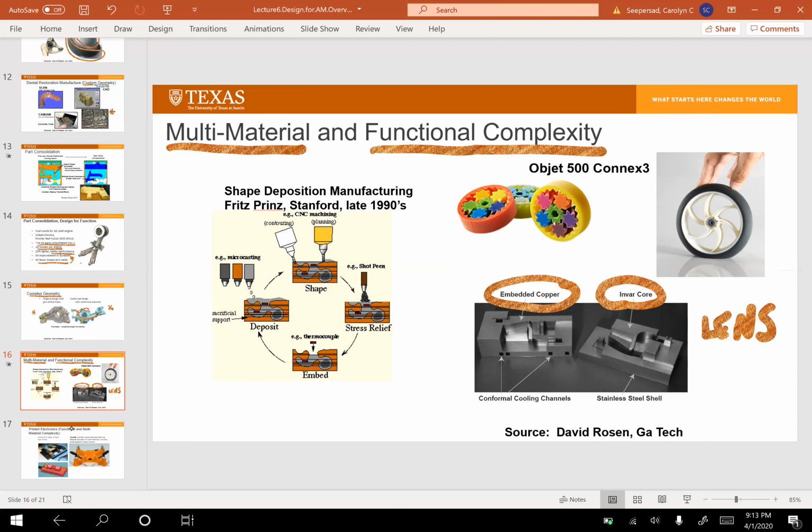You'll often find Invar used in supersonic applications sometimes. As aircraft move really, really fast and break the sound barrier, their skin starts to heat up. And if it all expands, then it becomes difficult to hold the joints together. But if you use Invar with a low coefficient of thermal expansion, you don't have such trouble with that.